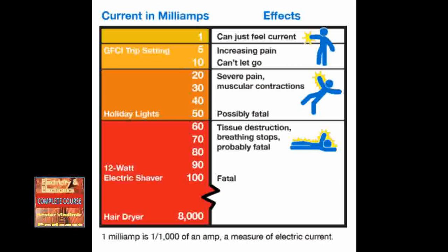Electric shock levels. A person can experience different levels of electric shock. These are rated by value of current flow and the effect each current value has on the human body. The values of current flow and their effects are listed in the following table. Current of 1 milliamp is barely noticeable. 5 milliamps is the highest harmless value, but can be painful. From 10 to 20 milliamps, there can be sustained muscle contraction. The victim cannot let go. From 100 to 300 milliamps, paralysis of respiratory muscles can be fatal, with severe internal and external burns, and can result in organ damage. 2 amps can cause cardiac arrest and is most times fatal.